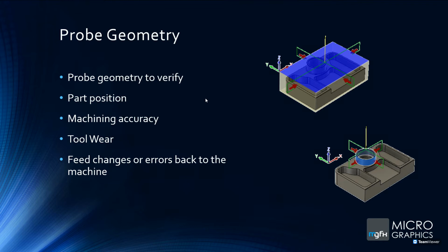Alternatively, it can also be used to feed back tool wear information to your machine. So each part can actually be checked, and as the tool wears down, that information can be fed back to the program, or should I say your tool wear on the machine updated to account for that when the machine is cutting.